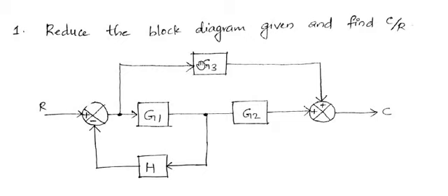But the signal that should flow to G3 should be Y only. As a result of shifting this branch point ahead of G1, the signal moving to G3 is YG1. So instead of YG1, the signal should be Y.